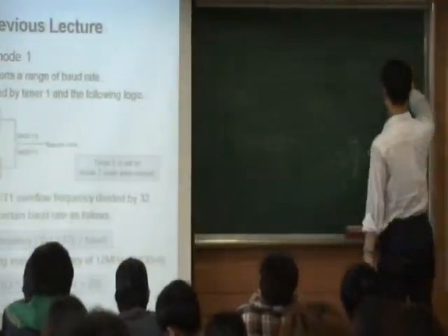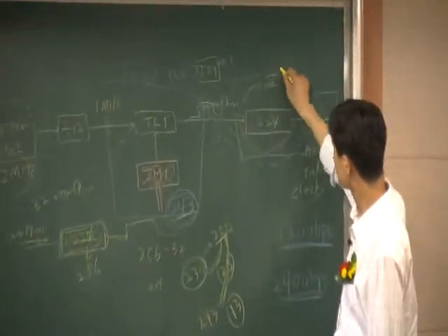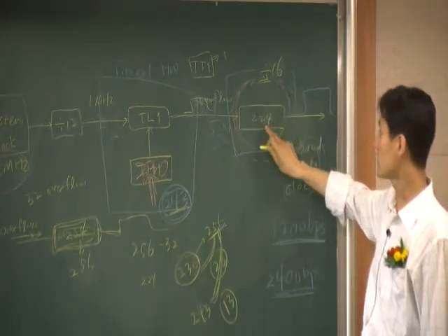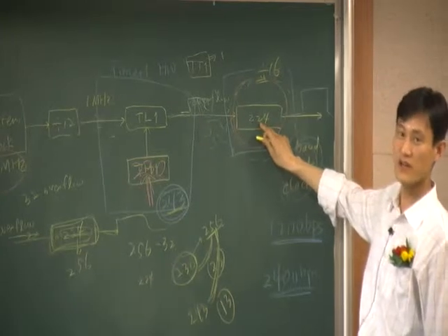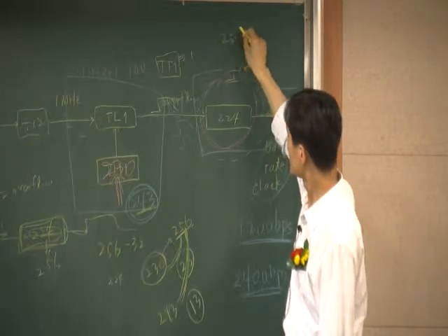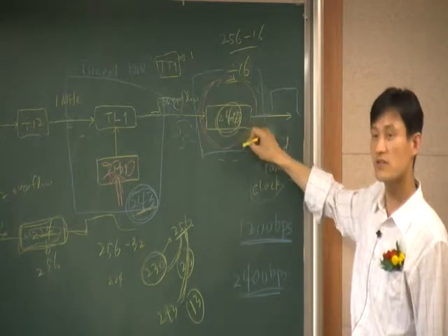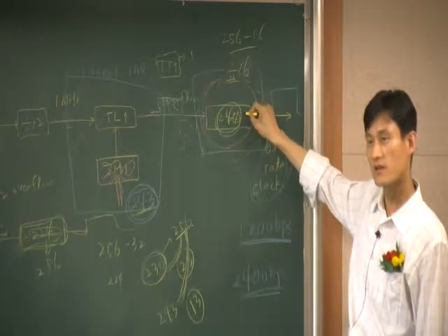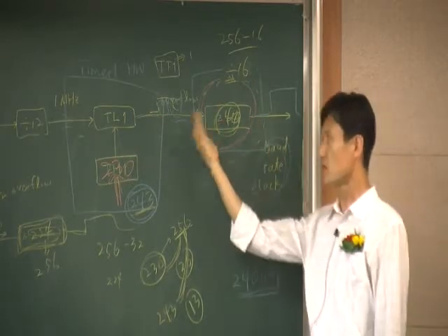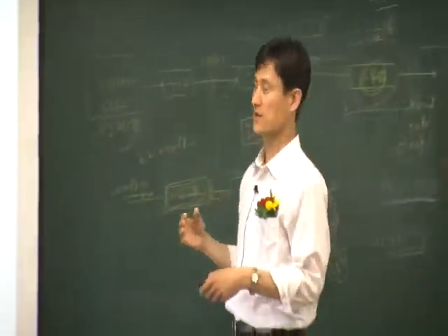So here, instead of divide by 32, now we are using divide by 16. Therefore, as I said, this is the same as a counter. Inside this counter, we no longer have the earlier initial value. The initial value for this particular counter is now going to be 240. That way, after 16 overflow, you have 1 output. So therefore, we can make it run faster.